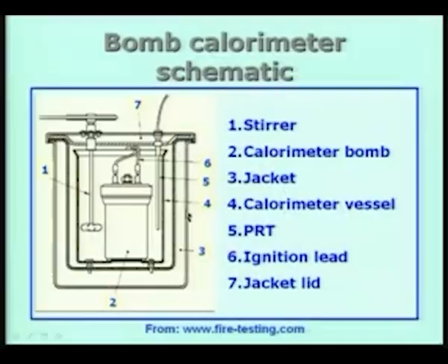That means that the temperature of the jacket is almost constant, equal to the temperature before the experiment starts. The reason why we have a jacket here whose temperature is maintained constant is to prevent heat loss, and therefore I can consider the inside vessel plus the bomb plus whatever is kept inside the bomb to undergo an adiabatic process. That means there is no heat transfer between the inner calorimeter and the outer jacket. This is the important thing to